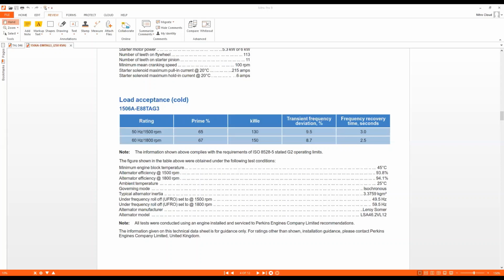So imagine you're driving a car at a high speed, at its full rated speed, and you suddenly, in a single moment, you drop down to a speed of 0. 100% brake. It will damage your car, it will shatter your car. So it's very highly unadvisable to apply 100% in a single step on any genset.